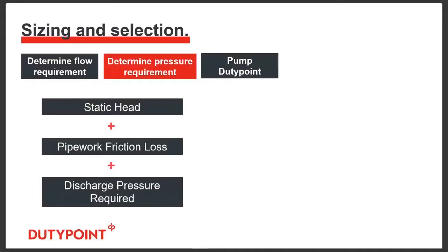Typically, you would take your lead from the sanitary fitting manufacturers, and they typically specify minimum pressures. But we tend to work on a rule of thumb that a good shower works at about 2.5 bar, but obviously take into account the customer's requirements as well. If it's a highly luxurious set of apartments or something, they might want slightly higher pressure.